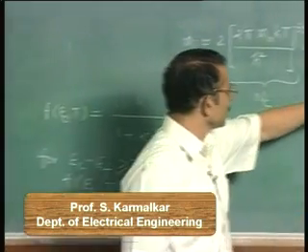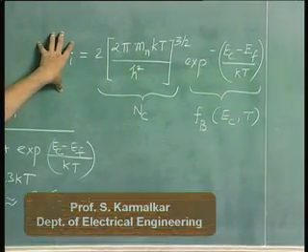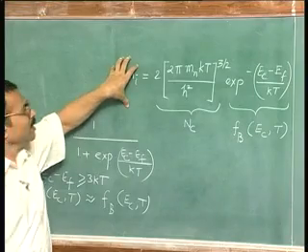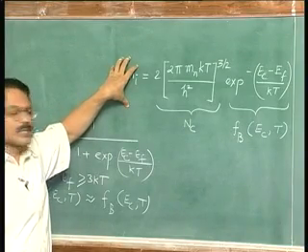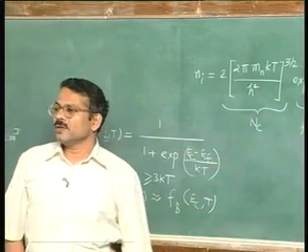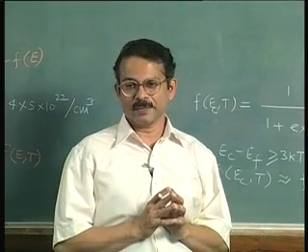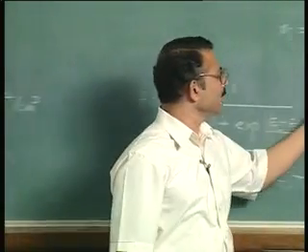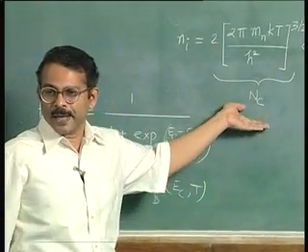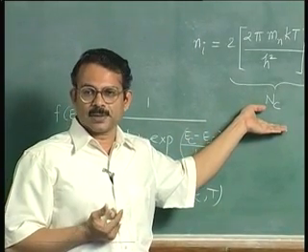If this is so, and if this is the number of occupied states, then it is easy to see that we could interpret Nc as the number of available states at Ec. Now please note, this is only an effective description, that is, it is not the actual description.